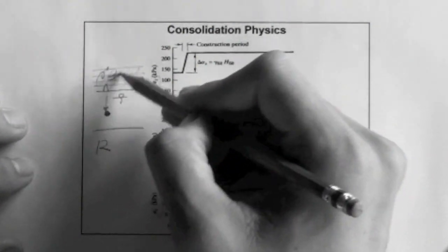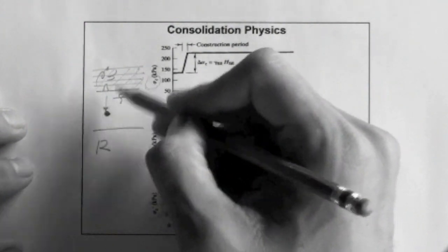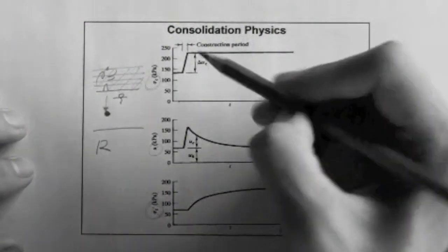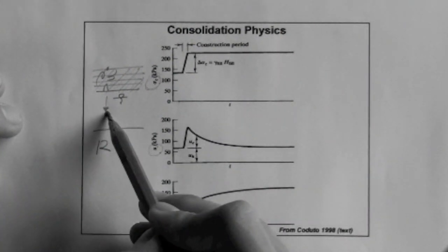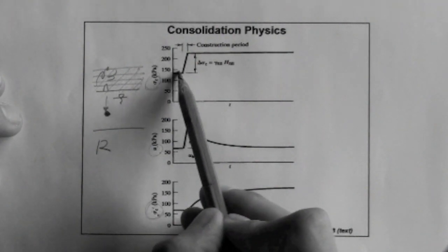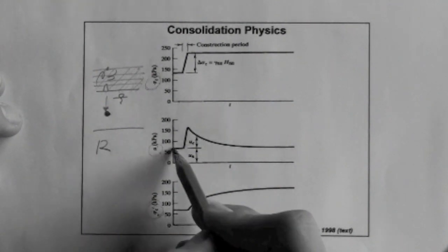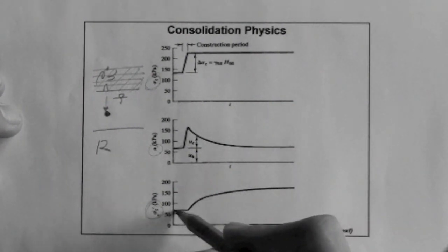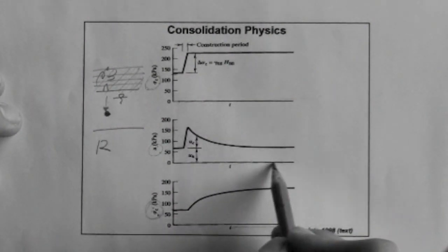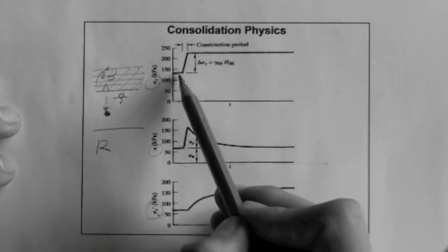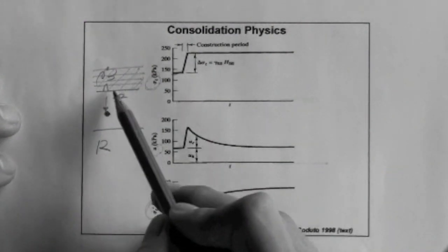So we get to the site before we start constructing, and we look at the point and we say, okay, we can calculate with the gammas, etc., and the location of the water table, the total stress, the pore pressure, and the effective stress at this point. And those are respectively 130, 65 and 65, let's say, right? Because this value plus this value is equal to this value. This is time, okay? So we get there, we're walking around the site, and of course, those three parameters are constant at this point. Then we decide to begin construction.